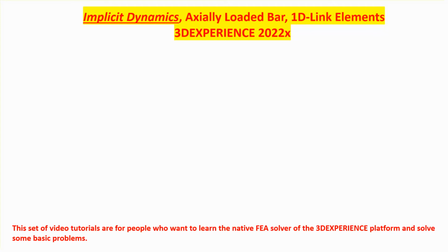Okay. Now, let me also remind you that there is also an explicit dynamics, which involves a great deal of impact and contact and nonlinearities, but you should have the license to it in order to be able to use that step. For now, I'm going to concentrate on implicit dynamics, which covers a wide range of applications, including pretty much all structural dynamics problems.